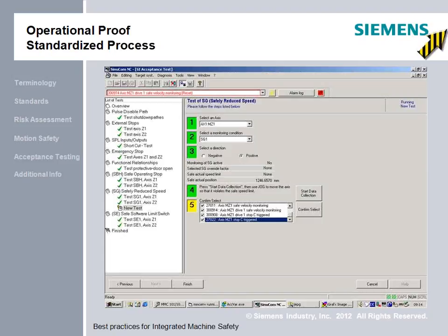It allows scripting of the test so that the test can be canned, so it can be executed multiple times by, let's say, someone that's not the safety system designer, that doesn't have the expertise in applications. This test can be canned and scripted so that it can be run, as an example, by a contractor brought in to help with acceptance testing.